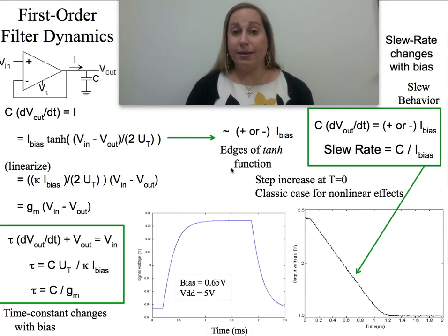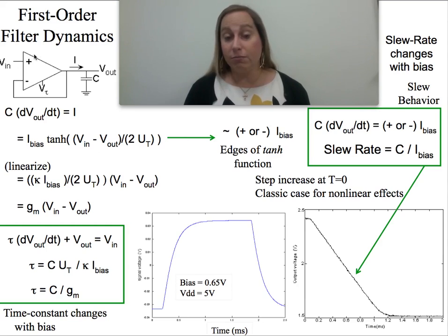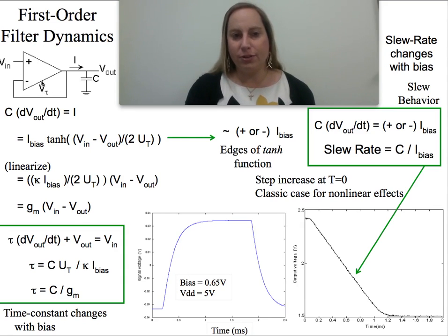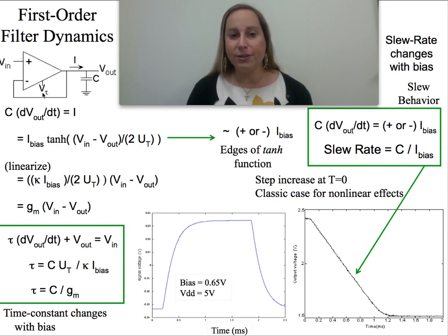And in fact, if it has first-order dynamics, it makes sense to actually use it as a filter, right? Instead of trying to make something and then make something more idealized. So these are the kinds of structures you would think about. Let's say I start with an OTA structure that we've been building, 5 transistor, 9 transistor. For today's discussion, it won't matter. It has a bias voltage for the bias transistor on the NFET, which sets a bias current, I bias. Then I'm going to look at the input-output voltage.